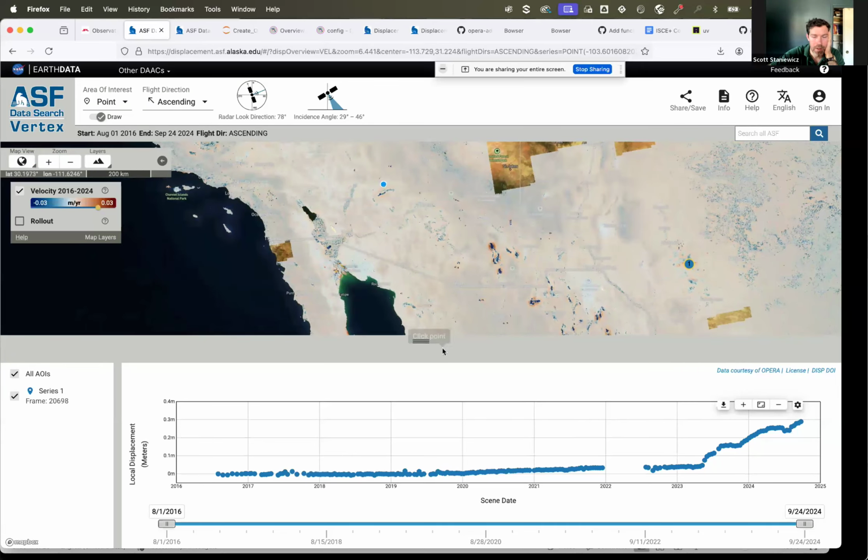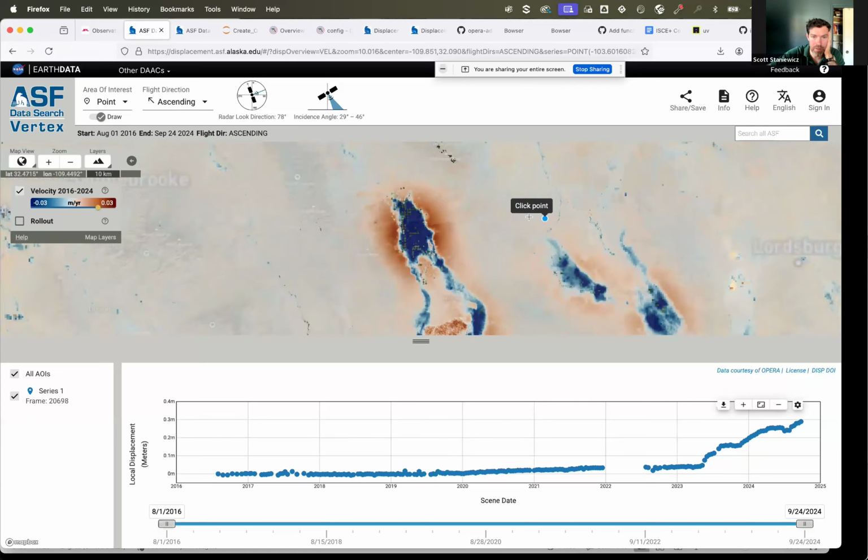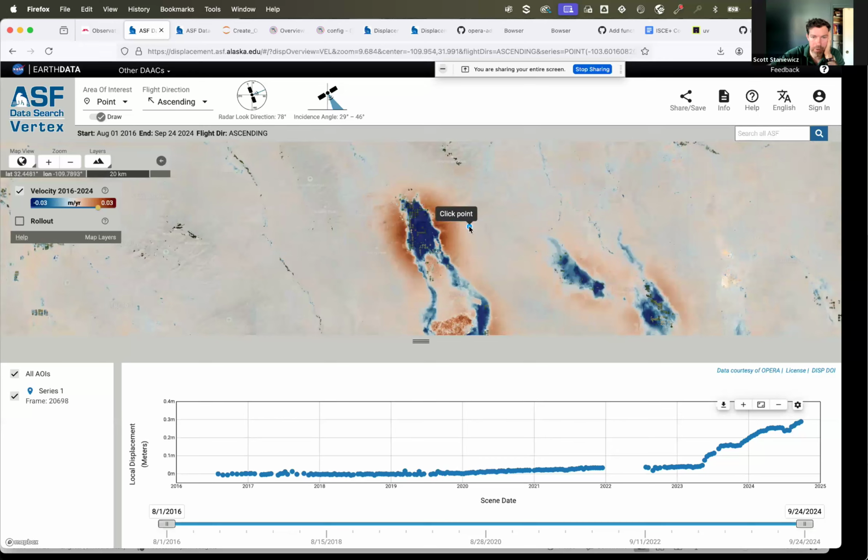When you have a sliding window filter that you're moving and subtracting, then basically your reference point is the average of everything there. That's another reason why you see these red shining boundaries around real subsidence. If you picture doing a moving window around this, the real signal is down, but subtracting the average brings the edges up a little bit. So that's one unfortunate side effect where it's not real uplift here, but it's a visualization artifact.